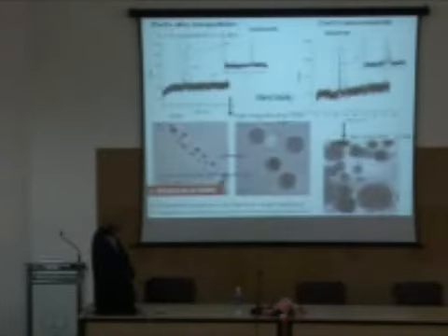Similarly, you can study copper cobalt alloys. You can make alloys which look like this, like a core and a shell, or you can make alloys like this, which are actually composites of copper and cobalt, and that you can easily find out using X-rays. If you have one peak, it is an alloy. If you have 2 peaks, that means you have 2 different metals.